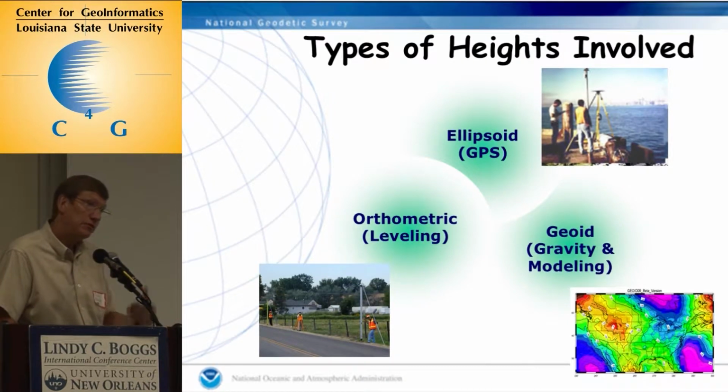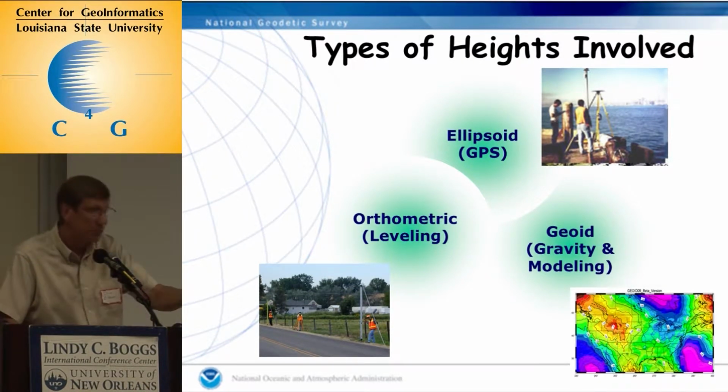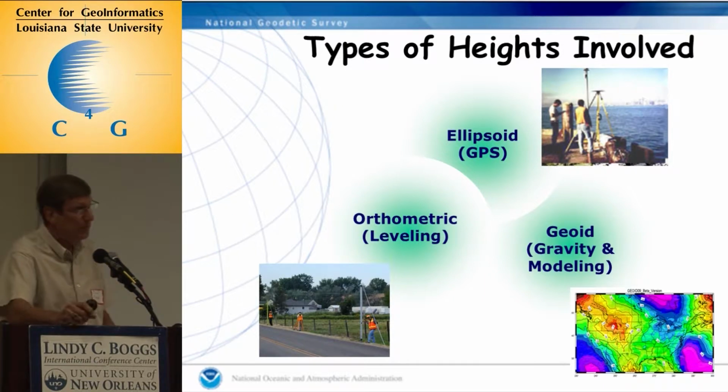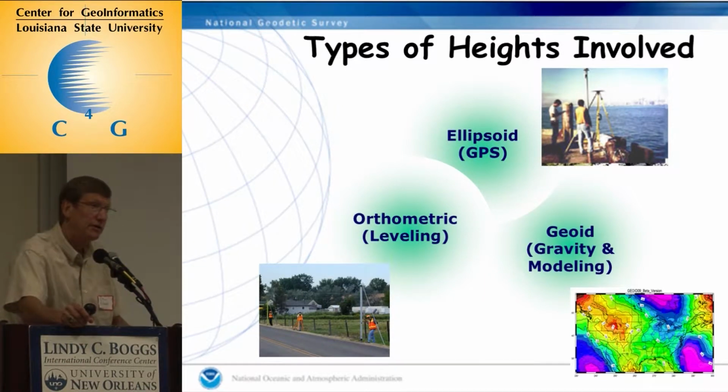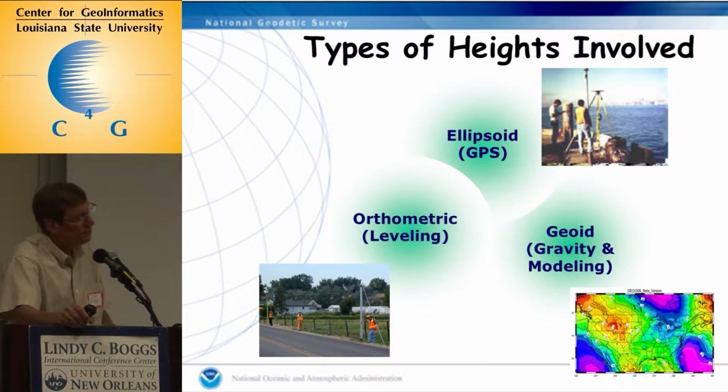And there are a lot of people that said, well, I put it into my machine, I ran it, collected the data, you plug it into a computer program, you apply some geoid model, and it gives you an orthometric height. And in many cases, in the beginning, they were just calling it WGS 84. But it gave you an orthometric height. So you have to know some of that.